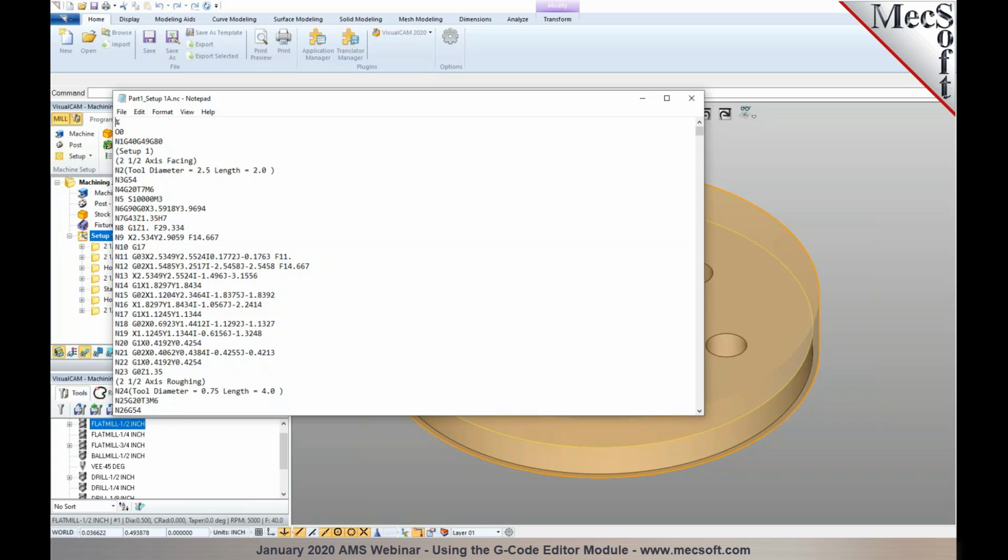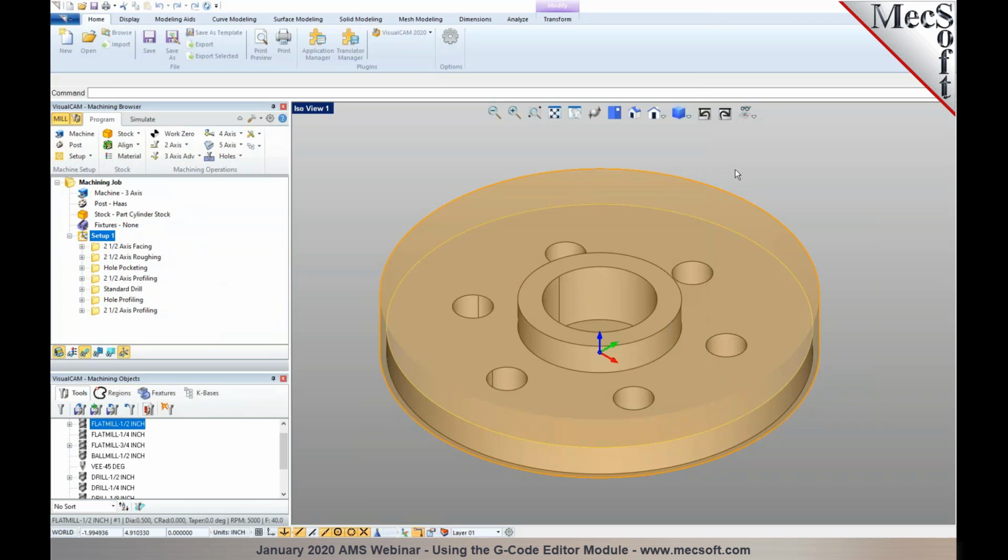And now we're going to use the G-code editor to verify and run a cut material simulation of the posted G-code. You might have introduced some additional parameters which you wouldn't be able to simulate in just a mill module. So I've just post-processed the G-code. I'm sure all of our users are familiar with this process up to here. So to switch from our mill module to the G-code editor, you could select... I want to interrupt.